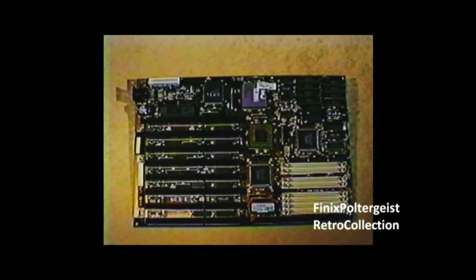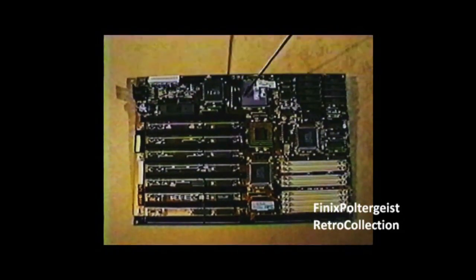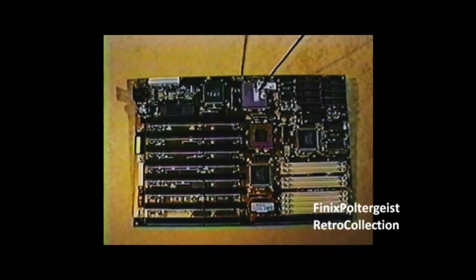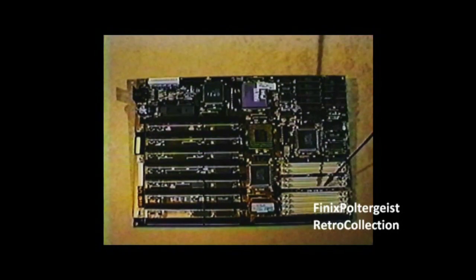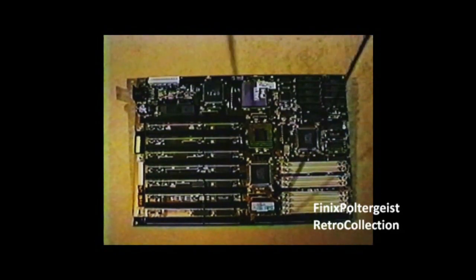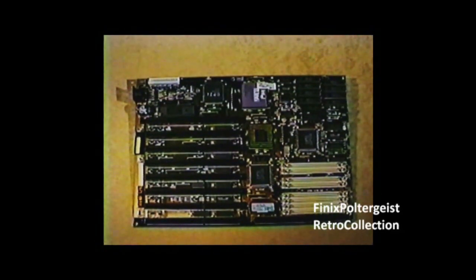Here is a 386-33 motherboard with a CPU that can be changed by plugging in a new CPU. It has a math coprocessor socket and cache memory which speeds the processing. The memory sockets are located here on this board. This particular board has 7 16-bit expansion slots and 1 32-bit slot which can be used for a memory card. You may recall that the 386 SX16 board we just saw didn't have a 32-bit slot.